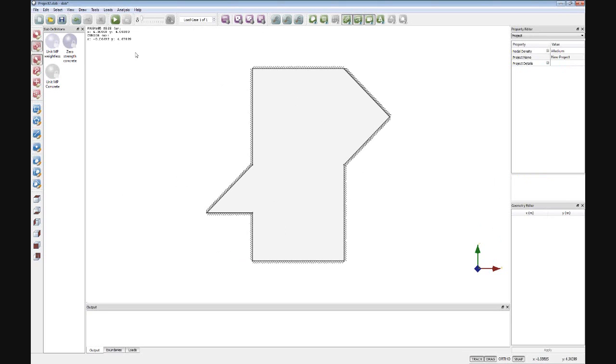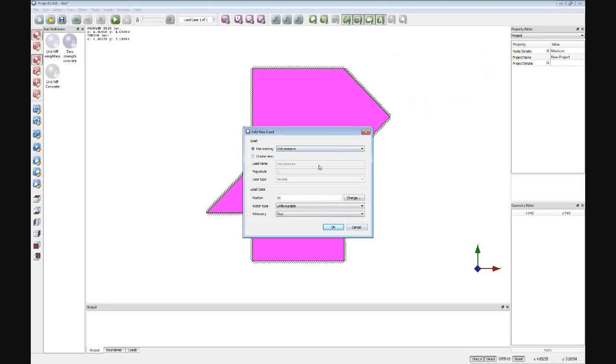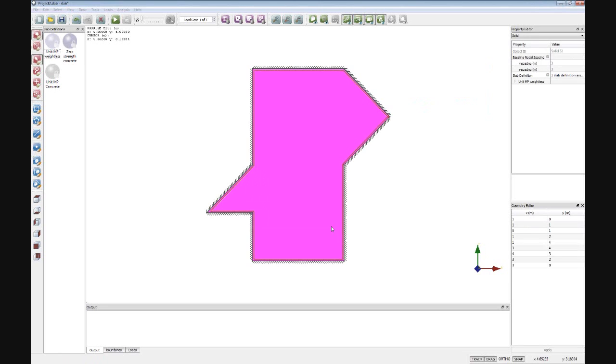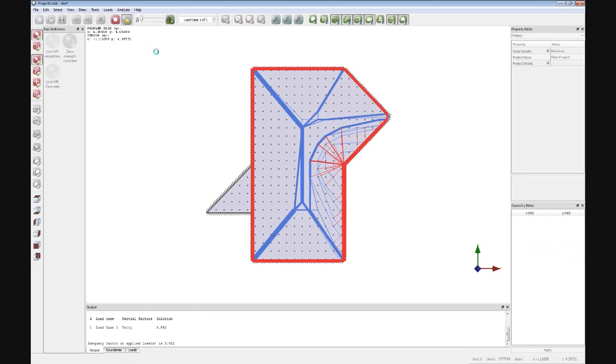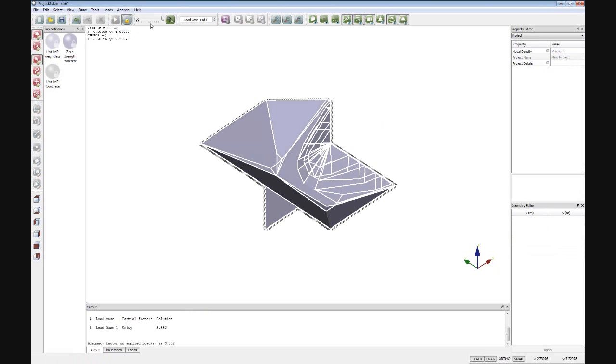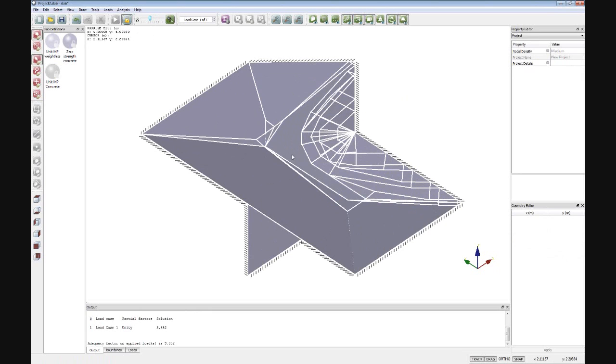What I now need to do is apply a material. I'm just going to apply a unit MP, so it's the benchmark material to start with, and I also need to apply a load. And I'm going to apply a pressure load, and I'm going to have a benchmark unit pressure load just for simplicity. I now need to click the green button, and straight away I get a yield line pattern, and the software will animate that directly after solve.